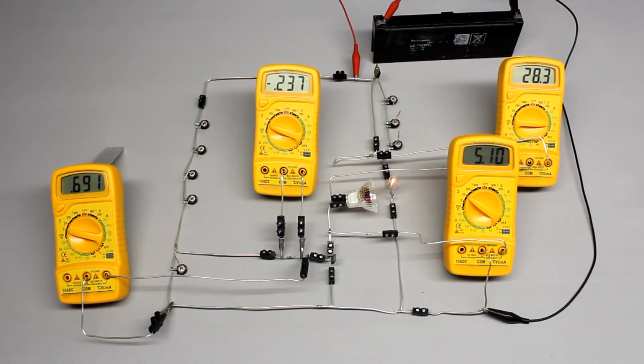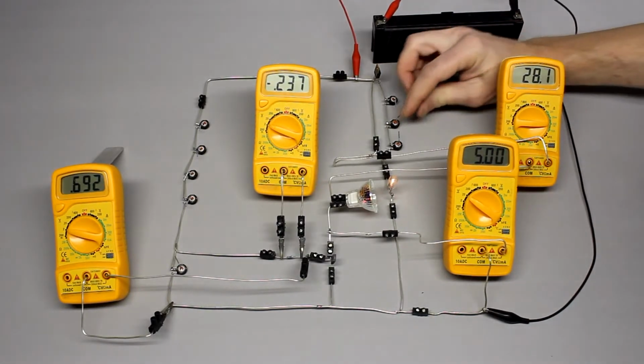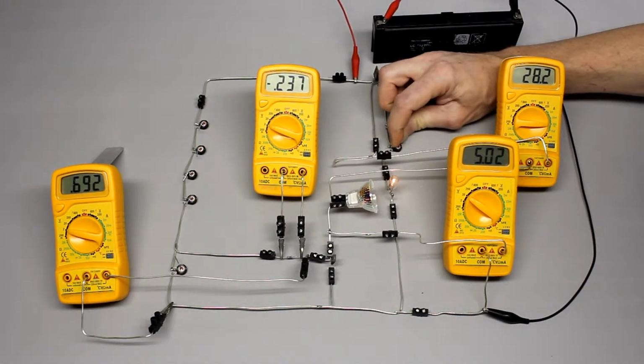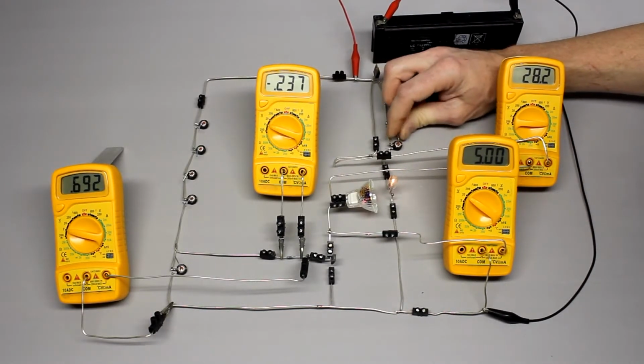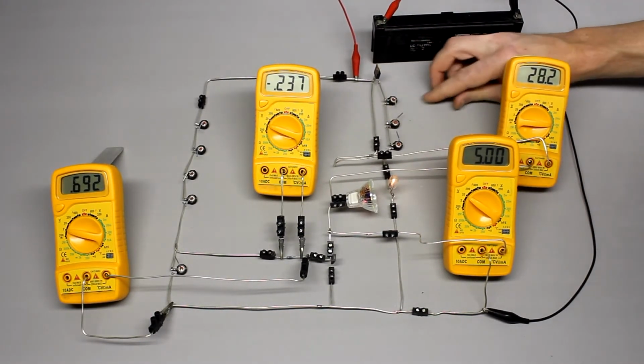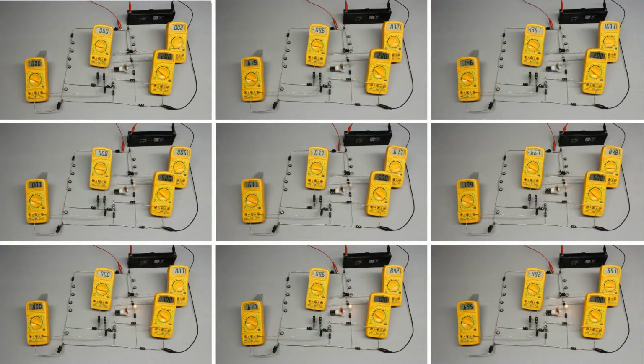This is caused by the heating of the filament lamps and the transistors, by which the resistance of those devices is altering. After some time has passed, the state of thermal equilibrium is reached, and we can start the series of measurement. The test series is repeated with a collector voltage of 2, respectively 7 volts.